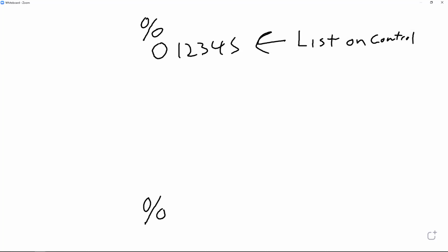Okay. That number, you don't have to save it as that number. You can save any program as whatever you want. Usually there's 2 different file formats for this: .txt and .nc. So when you save a program, and again I'll cover this when we actually program our first example, I save all my programs for the most part, if I'm doing onesie-twosie type work, as B dot whatever, because it's easier to type in.